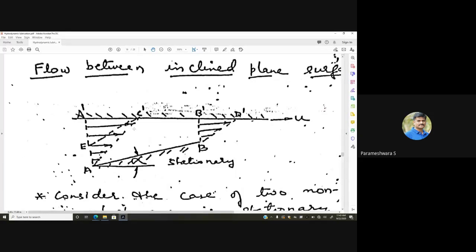As the fluid is incompressible, so air is compressible, no doubt about it, whereas the liquid is incompressible, and there is no end flow. The actual volume of oil carried into the space must be equal to the volume discharged from the space.